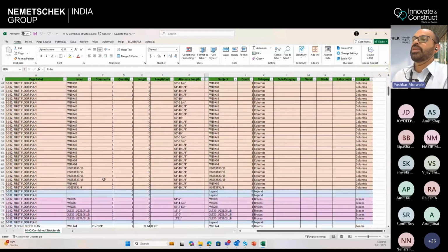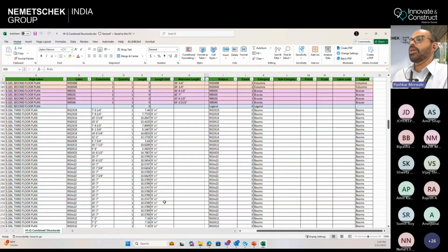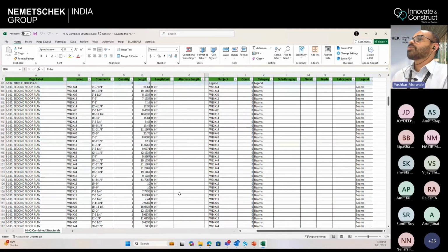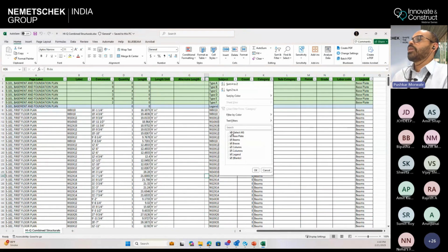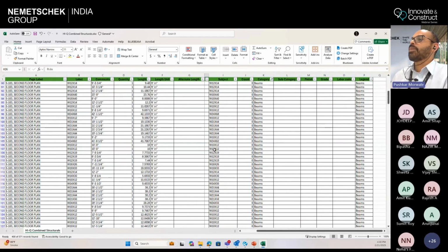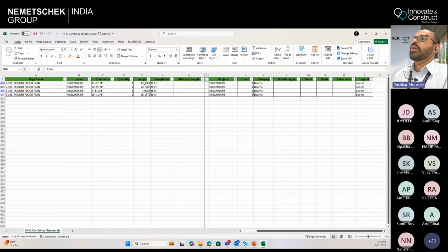Okay, and then from here you can filter out whichever quantities you want. So you can have only the category of the beams, for example. So all these are nothing but they are beams. As per the subject, say suppose you want to know how many HSS of this type are there. Okay, and then you can get the length for it.